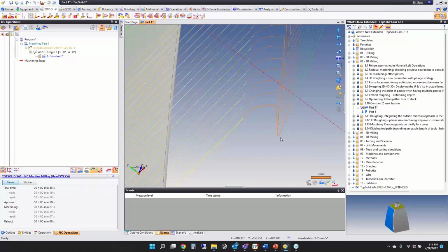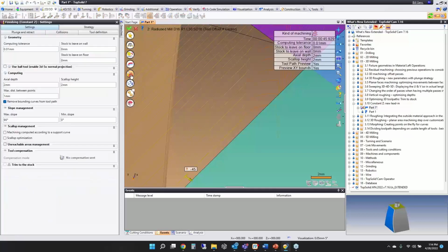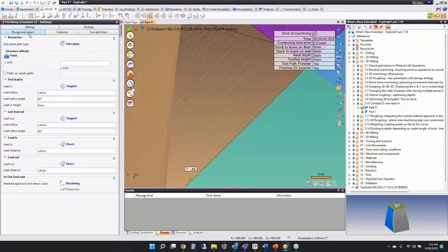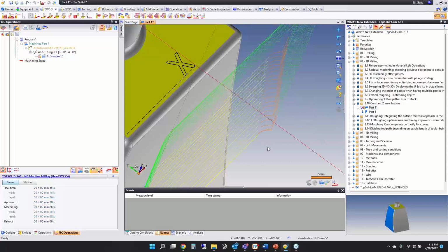The reason we include it is because if you're going to activate 3D compensation or 5D compensation, if your machine supports it, typically you need this vector shift in order to activate the 3D compensation. Some machines you don't, but at the end of the day, we've had people request that we don't want that. We just want the tangent arc alone, so we get rid of those extra little movements, just to have a cleaner lead in, lead out.